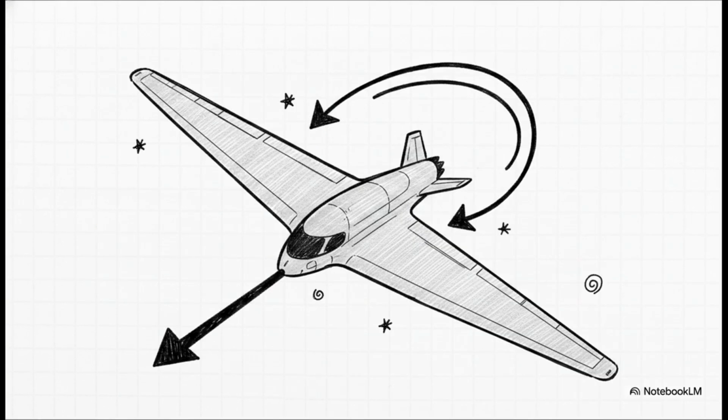The benefits of this are absolutely staggering. Because of that bell-shaped span load, the wing requires 12% less physical area, but allows for 22% more span. This translates into an immediate 12% reduction in overall drag. But the absolute crown jewel of this design, it natively produces proverse yaw.